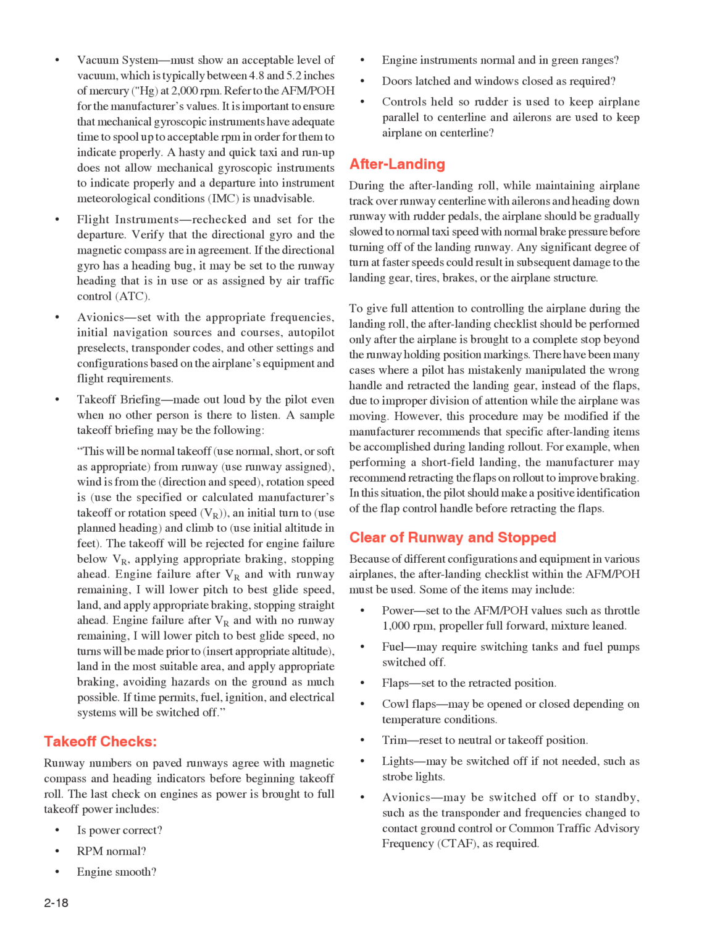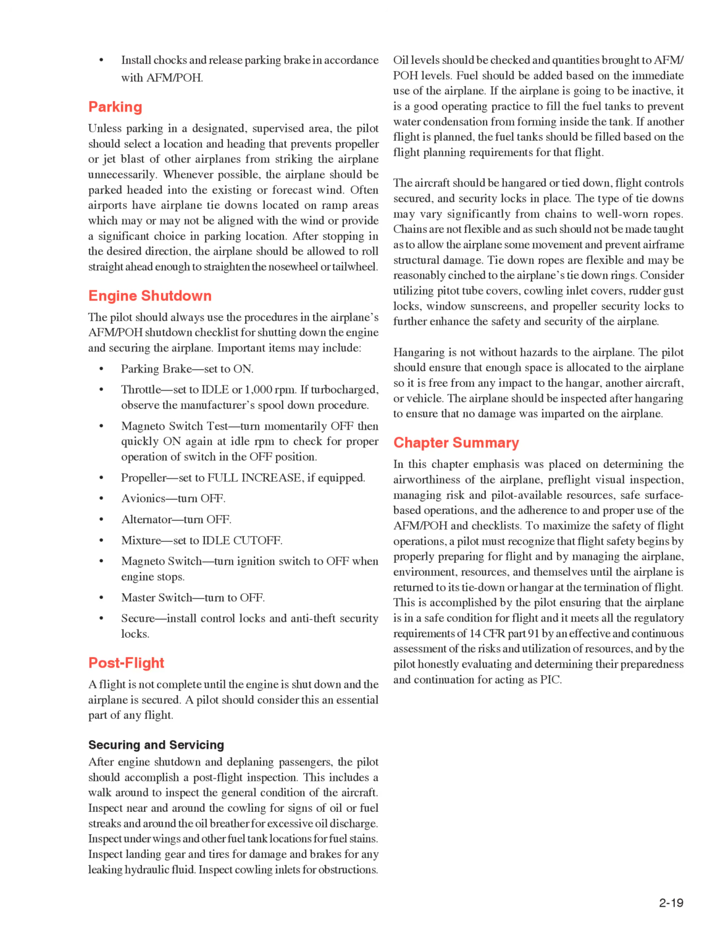Avionics, may be switched off or to standby, such as the transponder, and frequencies changed to contact ground control or common traffic advisory frequency, CTAF, as required. Install chocks and release parking brake in accordance with AFM/POH.